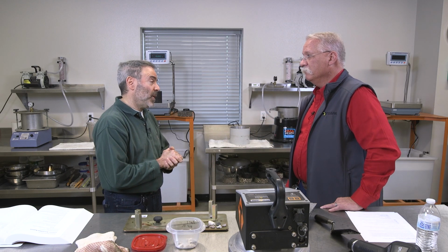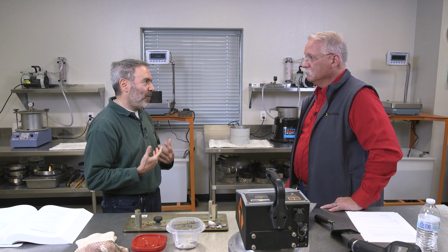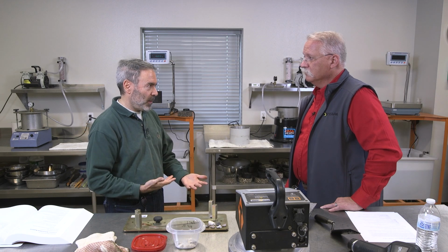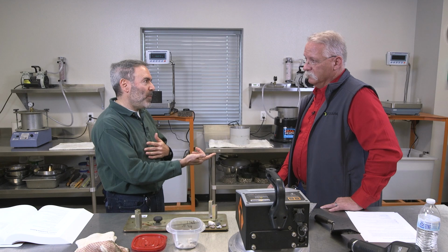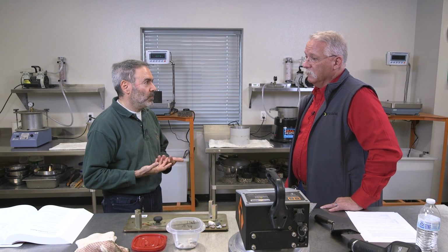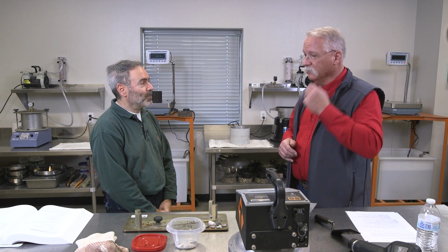Yeah, and temperature is an example. Our compaction procedure, the temperature is based on a PG binder. If you're certified, you have to know that. You're tested on that. You're asked that question. But if you're not, do you know that? So you may be molding at 250, but I have to mold at 290. That difference in temperature is going to make a difference in how the material compacts, which is going to make a difference in the test results, which is going to either cause us a problem or create a big problem. Acceptance, payment, everything. Everything. Good deal.